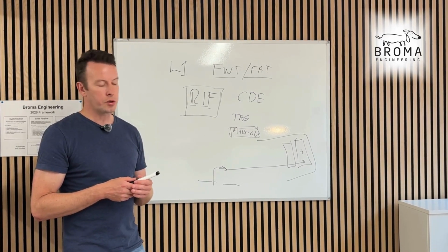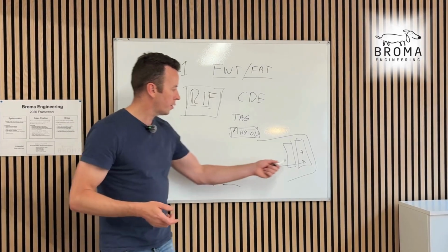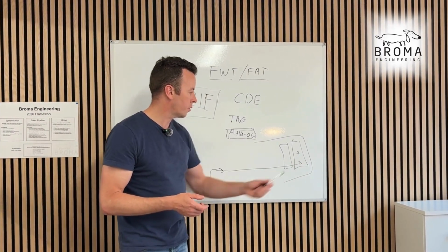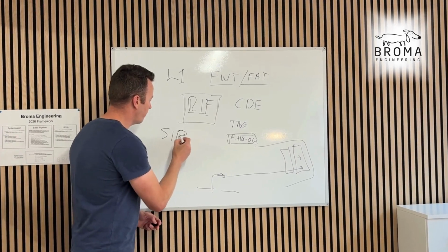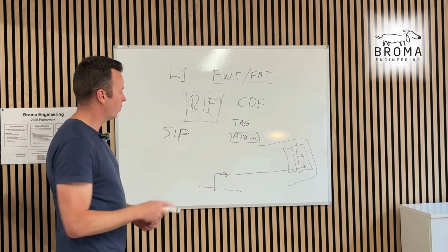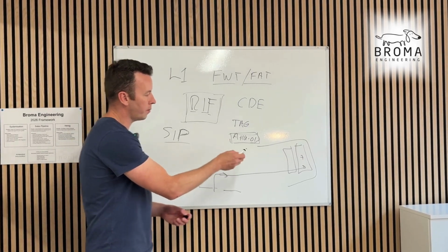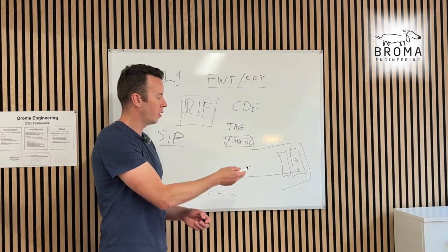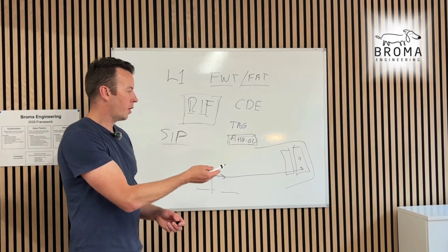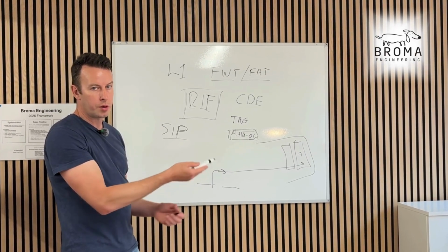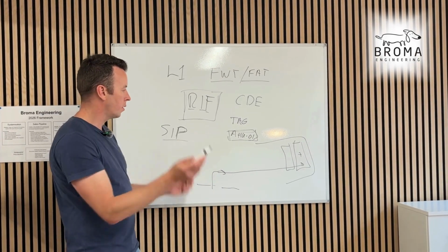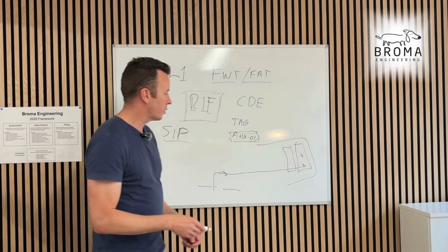And okay, let's presume now we've got it into place. It's now set in place. You can do your set in place inspection, SIP. That's another form. It's unwrapped. We're making sure that the right tag number is in the right place, that it matches the model, that there's no damage so far now that we've unwrapped it, that there's no water inside it, there's nothing weird, there's no bird after building a nest inside it or something.